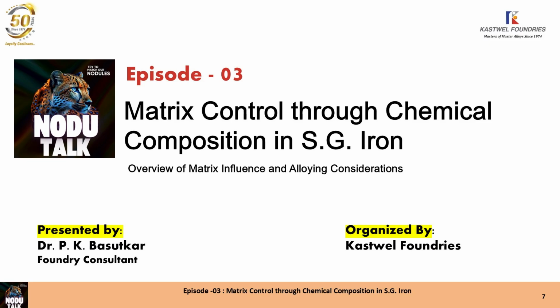Keep the inoculation level of 0.3 to 0.5% silicon using any good grade of ferrosilicon inoculant. The nodularity should be more than 85%. Matrix should consist of approximately 30 to 45% pearlite and the balance ferrite. Try to keep silicon at 2.4% max. At the same time, no carbide should be obtained in the matrix. Hardness can be increased by addition of about 0.3% copper, which will give about 30 to 40% pearlitic matrix. Now that we have answered this question, we'll start with the main topic of today.